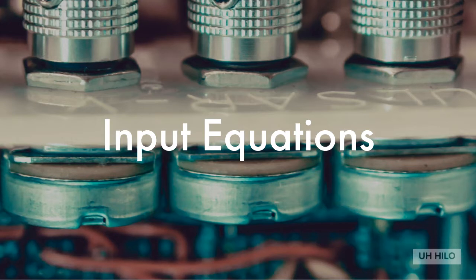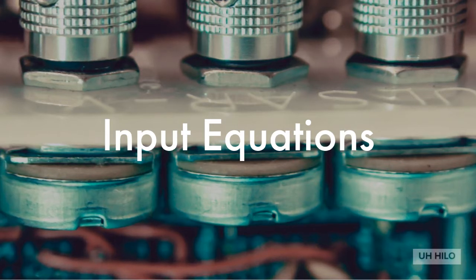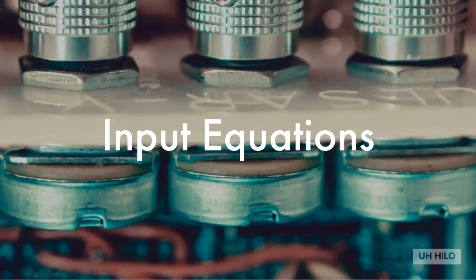A flip-flop input equation is a Boolean expression for a combinational circuit. The output of the combinational circuit is connected to the input for the flip-flop. Flip-flop input equations imply the type of flip-flop from the letter symbol, and they fully specify the combinational circuit that drives the flip-flop.